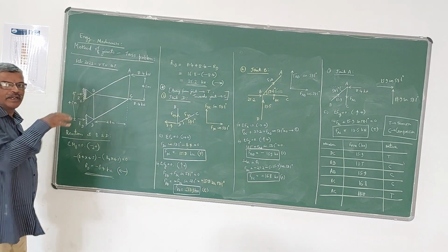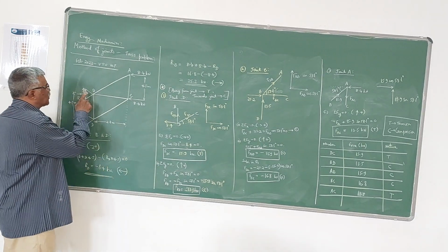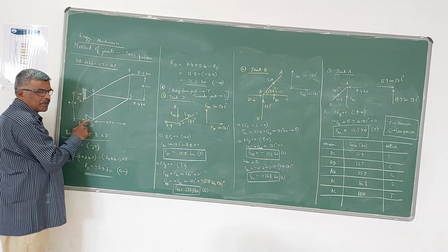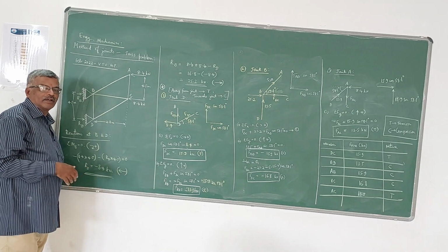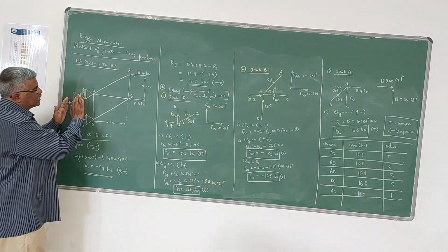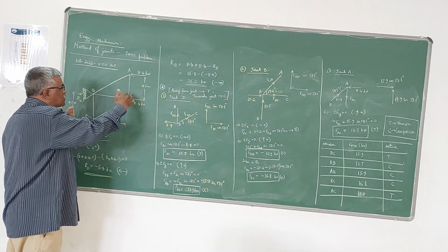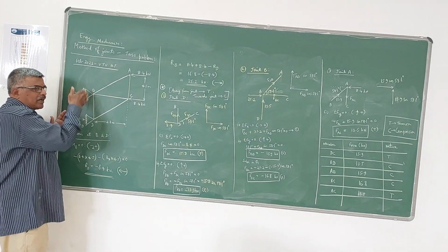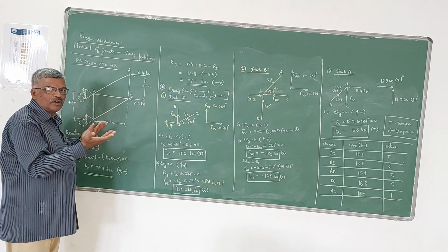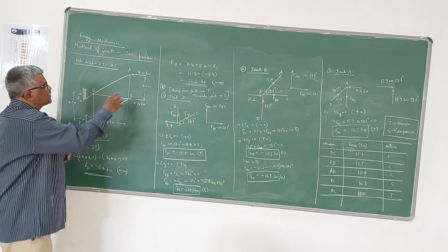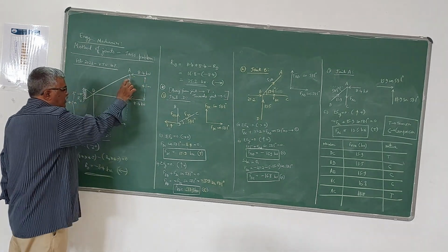If you see the truss configuration, it is a simply supported truss. There is a roller support here, there is a hinge support here. The loads are acting like this, and you can observe that the loads are only vertical loads. That means there are no horizontal loads, so there is no horizontal reaction here. The 8.4 kN and 8.4 kN are the forces acting at the given joints,